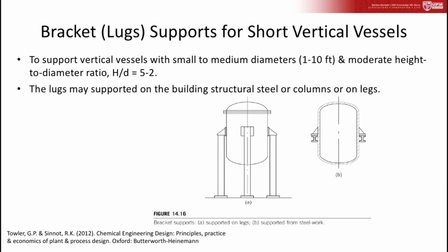If you are considering a skirt support, you need to bear in mind that you must make sure the area inside and surrounding the skirt is clean and dry, because the presence of water or a too humid area inside the production area is not good due to the risk of microbiological hazard. We don't want this microbiological hazard to be transmitted into our food product.